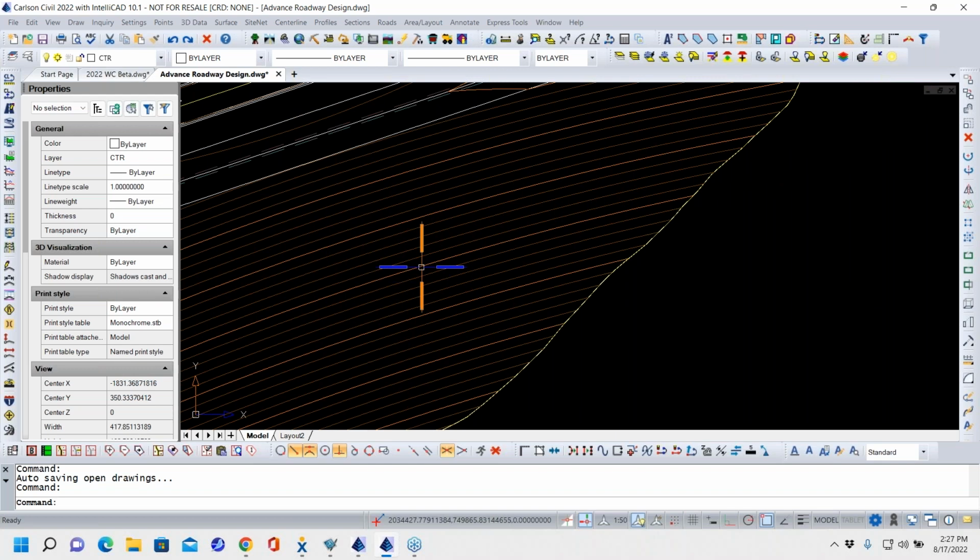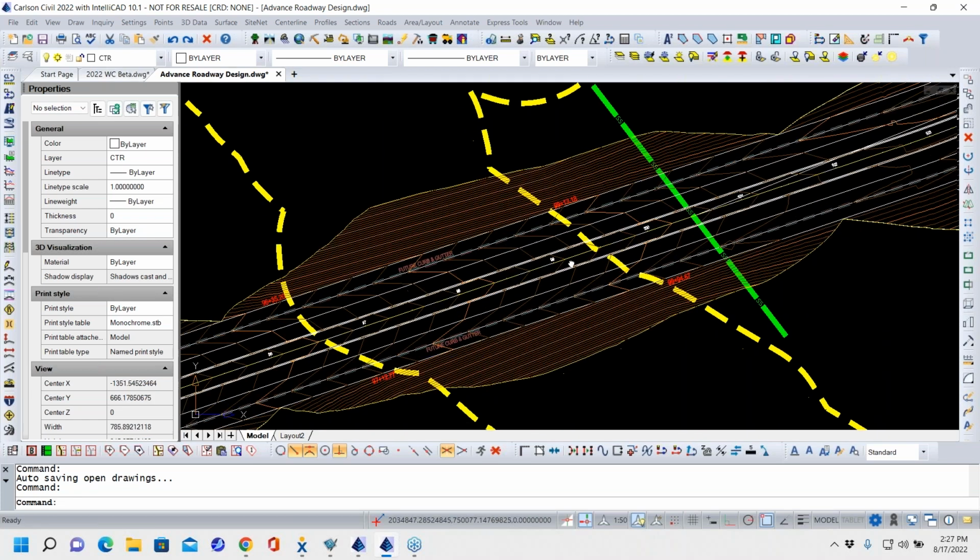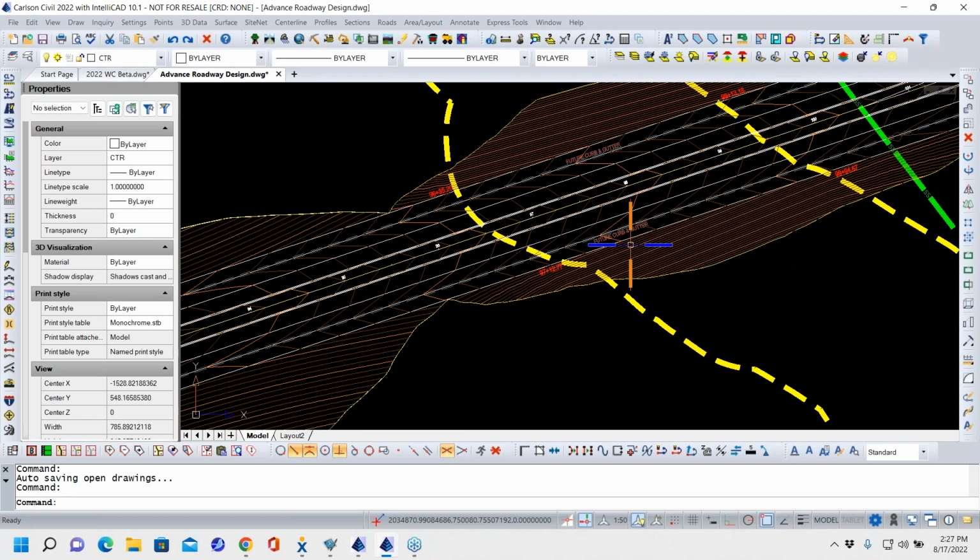In this case, I made it exaggerated so you guys could see a difference. And this is 5-to-1. But when I come up to a Neuse River buffer, then I need to program to bring my toe slope not from 5-to-1, but to 2-to-1, and tighten this up in here as tight as I can.